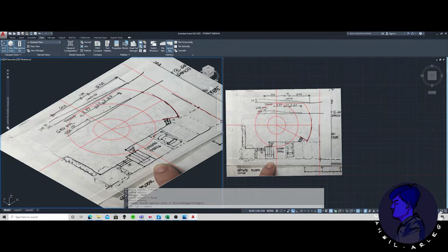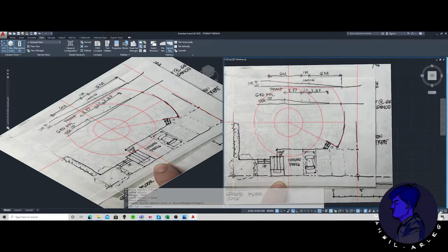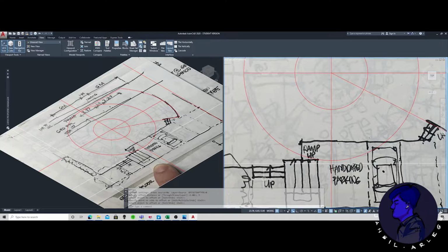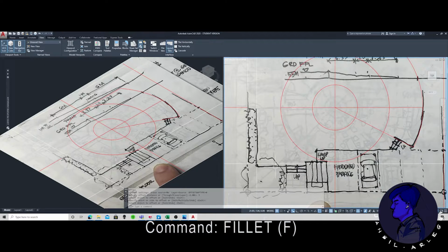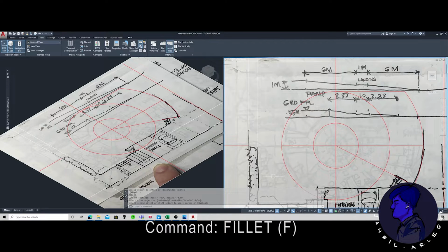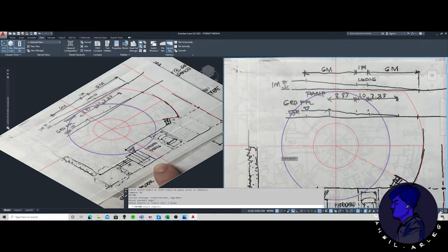Now, the base of this is going to be about 0.55. So I'm going to generate that. So offset 1 meter. So pretty much, I know the dimensions here. Let's sketch this. Yes, that's actually a 3 meter line. Fillet. Into a corner. So this is going to be the alfresco area. Extend that. Use that line. Fillet.